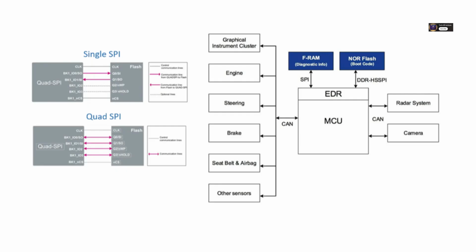What happens after sending the data? After the last data byte is sent, pull CS HIGH, but you're not done. Now comes the critical part. You must poll the status register. Send the read status register command repeatedly. Check the WIP bit, write in progress. It will be 1 while the chip is busy internally writing the data from its buffer to the flash array. You keep checking it until it goes back to 0. Only then is the write operation truly complete. Right, gotta wait for that WIP bit to clear.